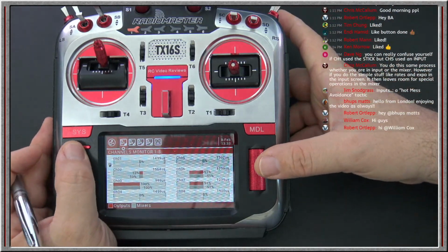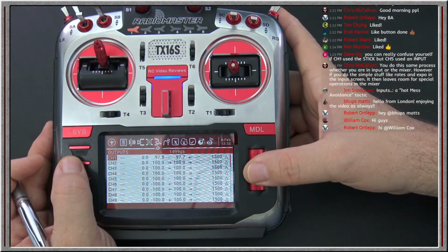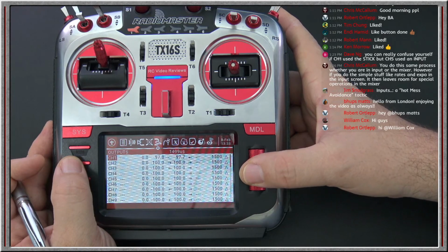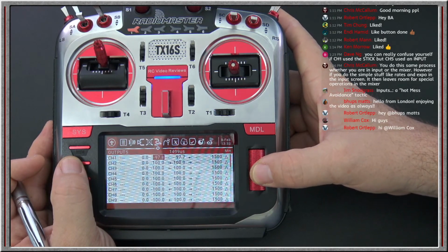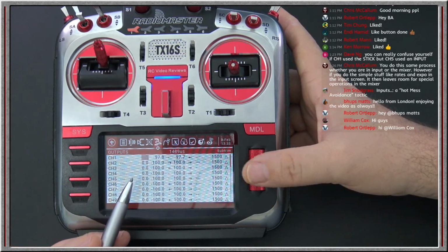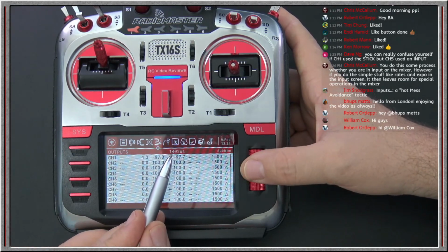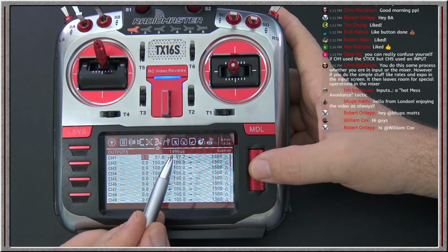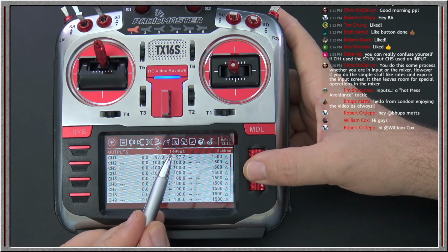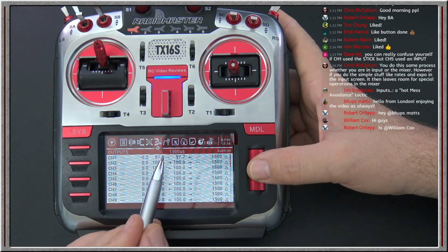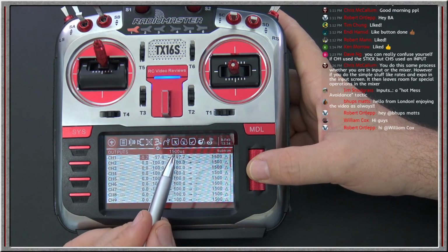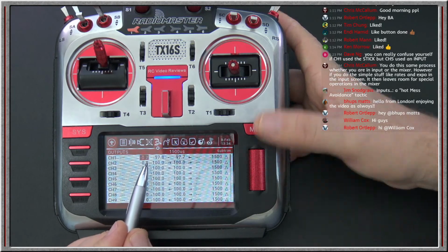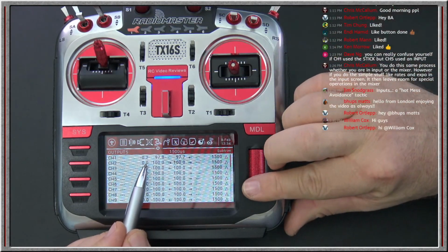And then regarding center, I actually have a whole video on this. We did trims versus sub trims. I'm not going to go into the specifics of that here because I do actually have a full video on that. But if you need to change your center position, notice that right here, if we have it at 0, notice that the output center on, well, look at that. It needs a 0.2, but to get it centered at 1500, you need it at, on this particular setup right now, you need it at 0.2.